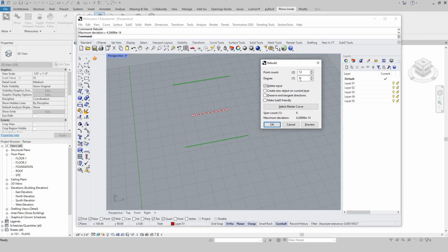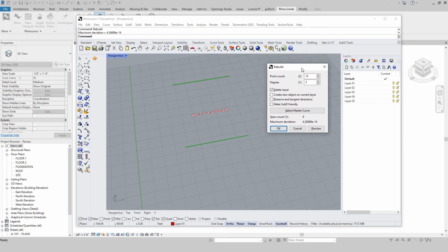Degree 1, degree 2, and degree 3 curves are all different kinds of mathematical formulas. The geometry in Rhino is more pure than most geometries in most programs. What I'm saying is that mesh geometries are very common in most computer-aided design programs. However, Rhino geometry is more pure. If you're familiar with graphics, raster images are pixelated, right? And that's kind of what mesh geometry is. It's triangles and squares, 4-sided and 3-sided polygons.